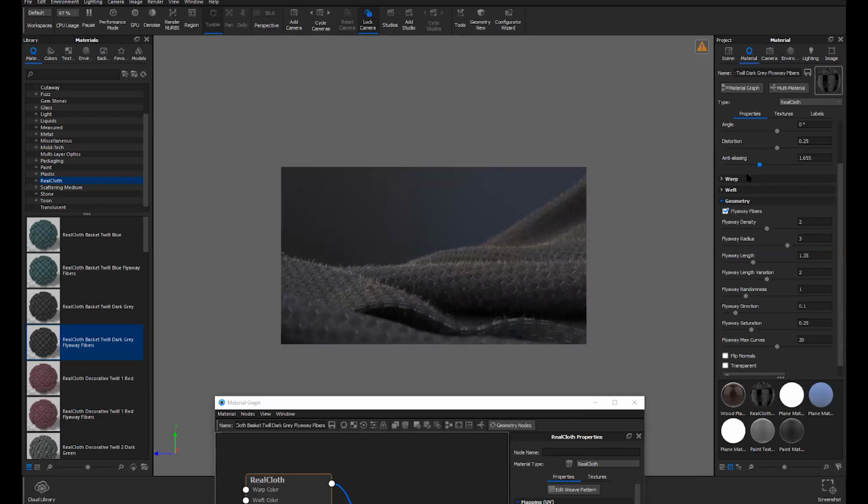And you can solve that by cranking up your anti-aliasing. You don't need to go too much at the beginning, but start at like 1 and then go up from there to see if you're getting those effects. Usually if the pattern's somewhat large like this, you're not gonna experience that. But if you're getting really tight patterns or you're far away from your material, that is something that you're most likely gonna encounter. And that anti-aliasing is how you're going to be able to combat that.